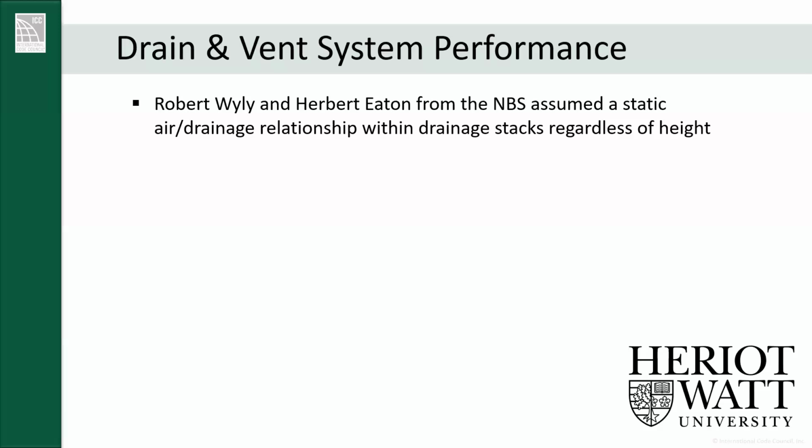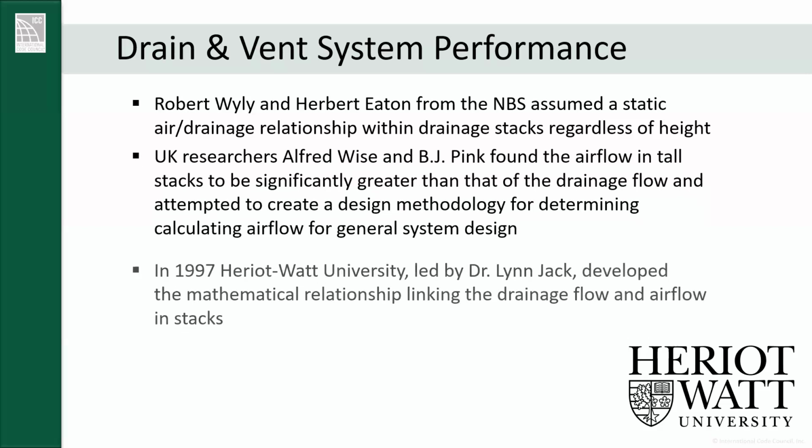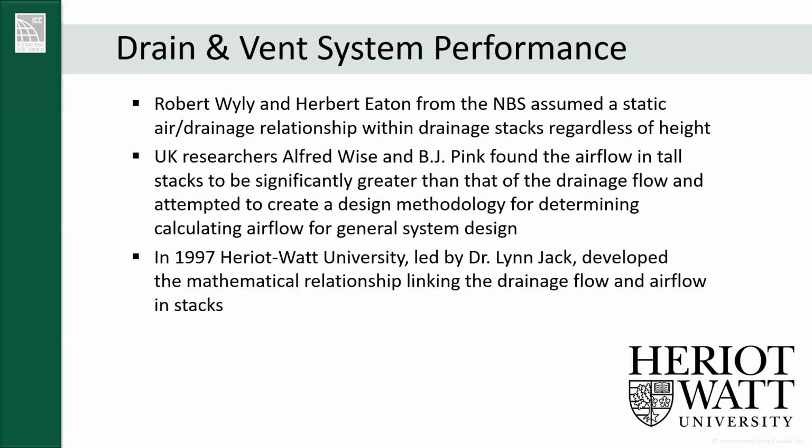So there's a couple of researchers at the National Bureau of Standards that assumed that the relationship between static air and the drainage flow within the drain stacks were equal regardless of the height. Right? It was later found that in tall stacks, it was significantly greater than that of the drainage flow. So the airflow was actually significantly greater than the drainage flow.